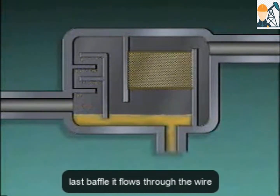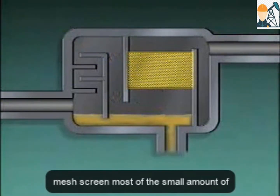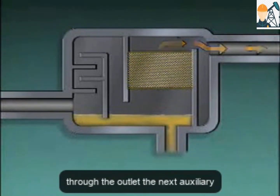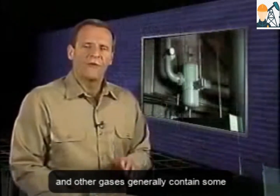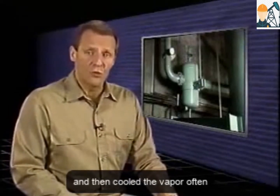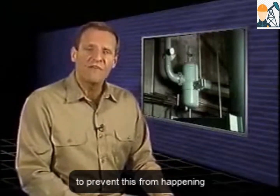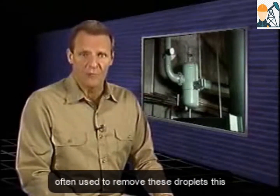After the gas passes the last baffle, it flows through the wire mesh screen. Most of the small amount of remaining oil is trapped by the screen and then drips into the sump. The relatively oil-free gas continues on through the outlet. The next auxiliary device we'll look at is a demister. Air and other gases generally contain some moisture vapor. When gases are compressed and then cooled, the vapor often condenses into liquid droplets that can damage some types of pneumatic equipment. To prevent this from happening, moisture separators or demisters are often used to remove these droplets.